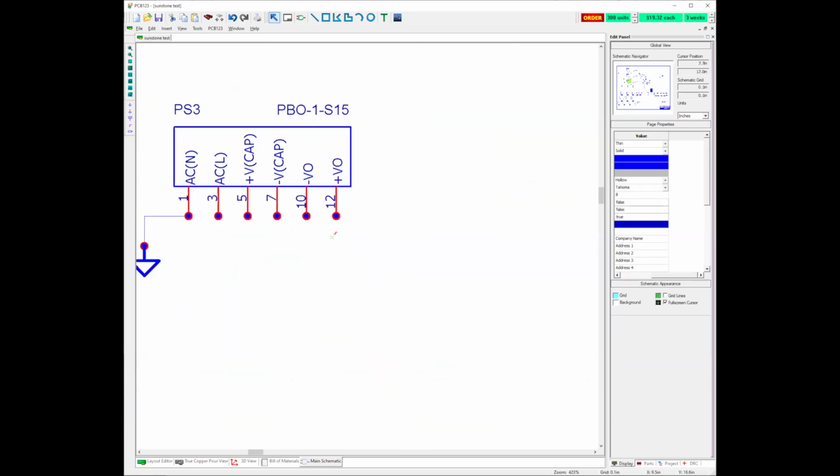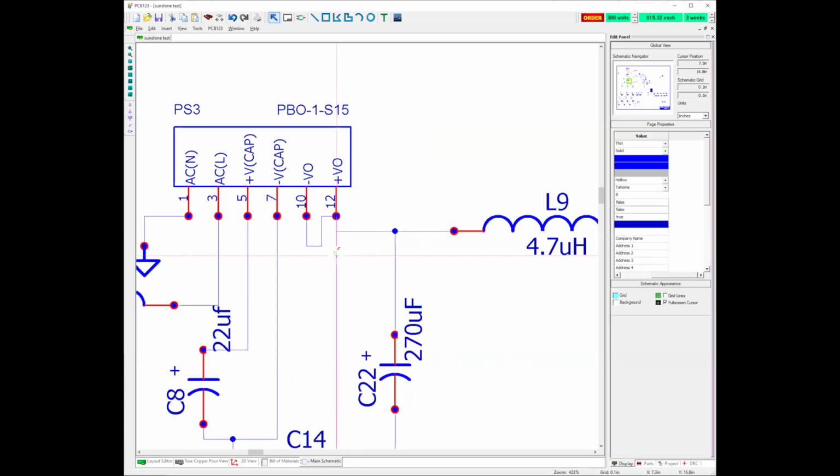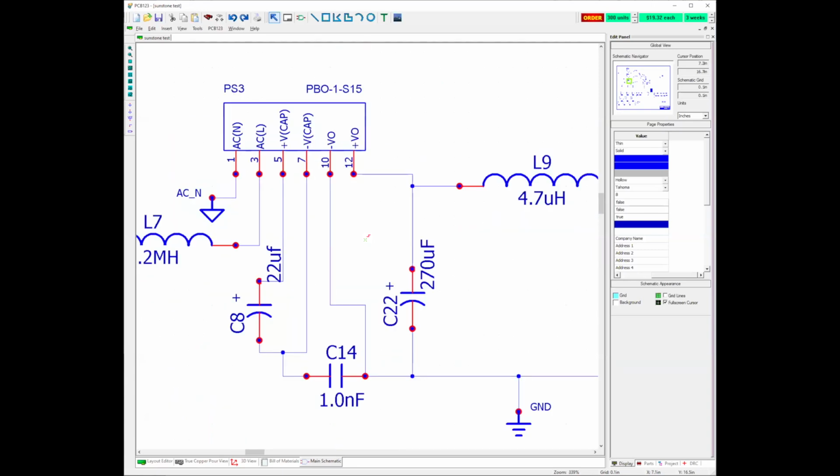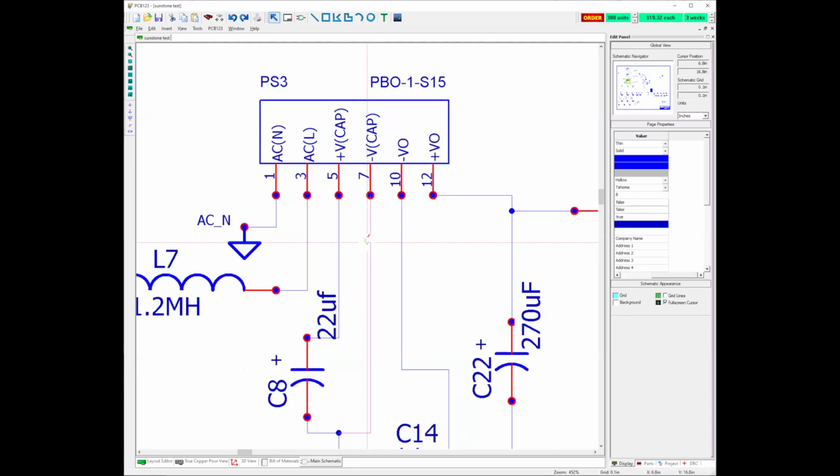And it's really hard to decide which segment I want to delete in order to correct that mess I made for myself. This can be a huge problem if you've got a part like a 24 pin connector, and you short 6 pins together, and suddenly you've got 6 nets that are incorrectly named, and it just makes a terrible mess of your net list. So let's put it back where it was. That's something you just have to keep an eye out for.